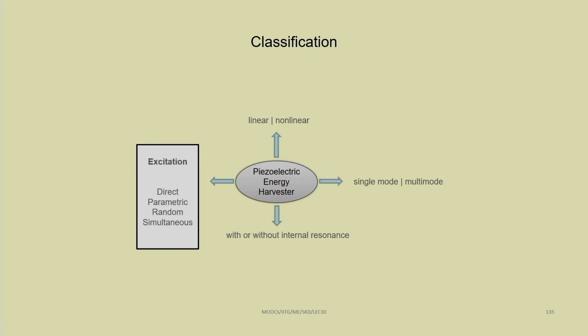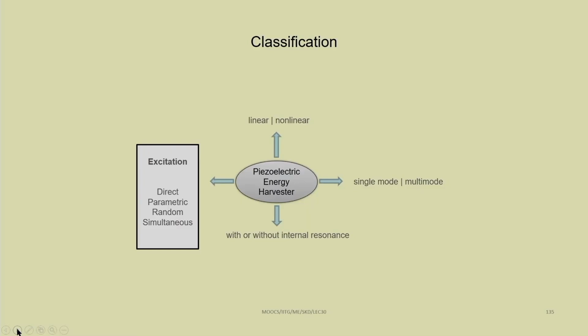If we are not considering internal resonance conditions, only single mode approximation may be possible, but when we consider internal resonance, we go for multi-mode approximation and take an appropriate number of modes, particularly when modeling the system using the finite element method. So, we can easily analyze the system for different resonance conditions.